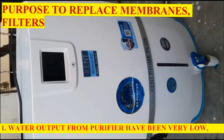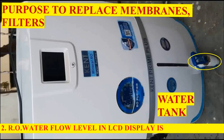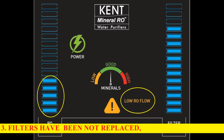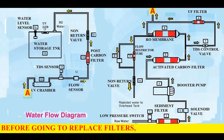Number 1, water output from purifier had been very low, it is taking 1.5 hours to fill water tank. Number 2, R.O water flow level in LCD display is indicating very low. Number 3, filters had not been replaced for 2 years. Before going to replace filters, let's study the water flow diagram of Kent Prime Plus water purifier.